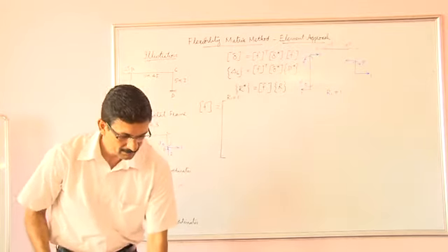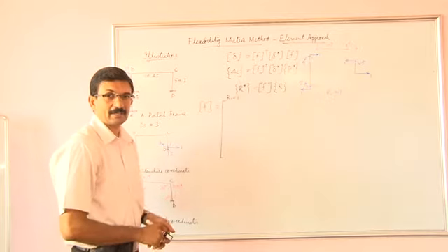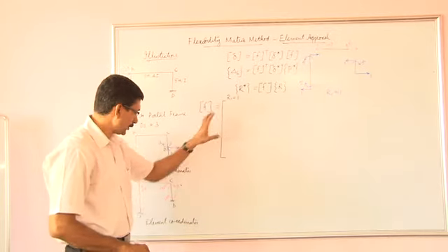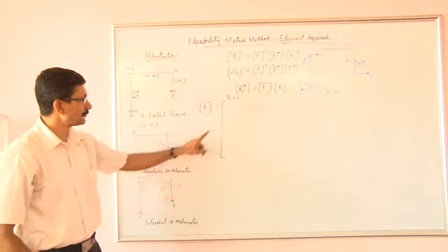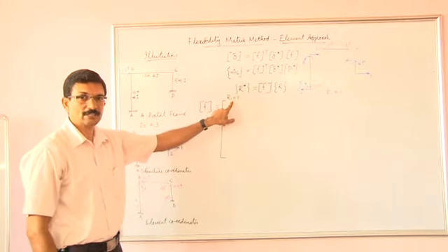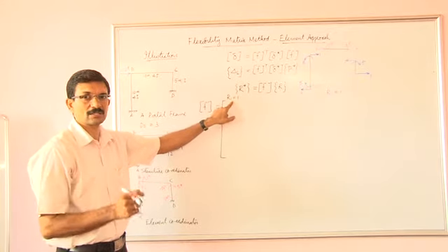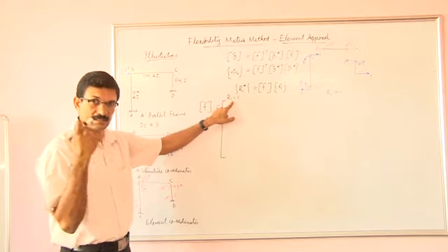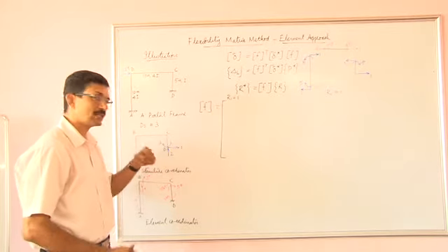Now we can fill up the first column of the F matrix, which will contain essentially the forces corresponding to element coordinates when we set R1, the force corresponding to the first structure coordinate, equal to 1, and the forces corresponding to the second and third, the rest of the structure coordinates, are 0.